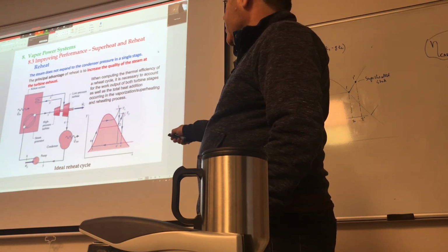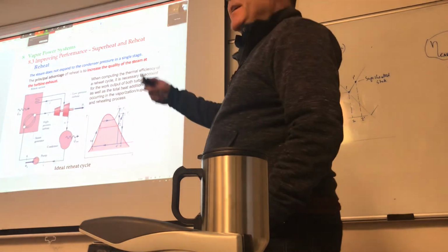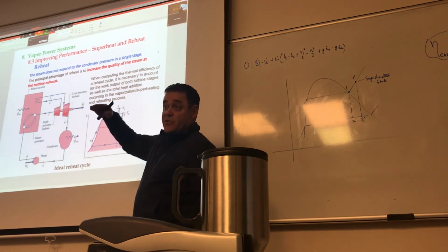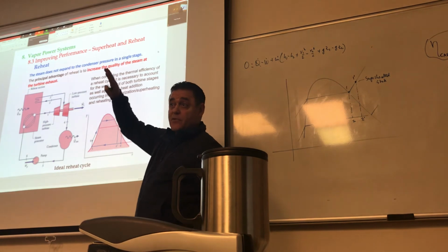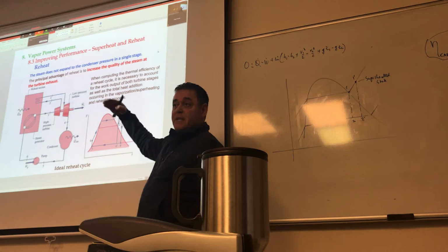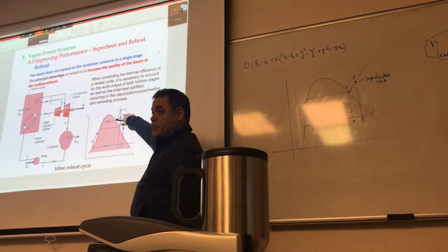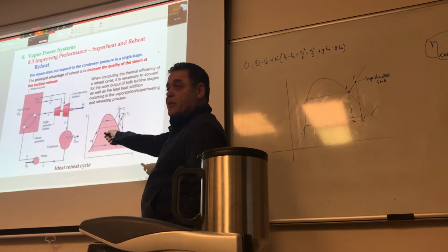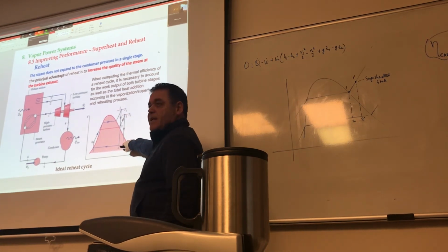And then what's happening at 2? You're passing it through the heater again, so you're reheating it. As you reheat it, do you agree that it's reheated at constant pressure? Because remember our basic assumption, any flow through a pipe is a constant pressure thing. But the end result would be just a temperature increase. So you increase it now to temperature number 3, to temperature T3, as it exits the reheater. And then you expand it through the second stage turbine, which brings you down to that state, and everything else stays the same.